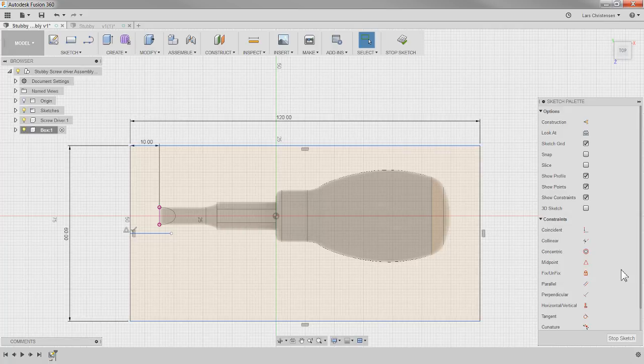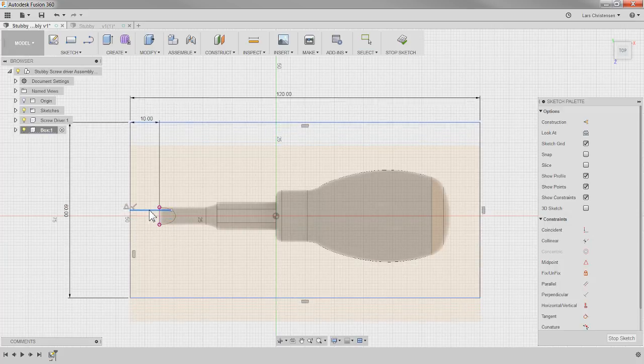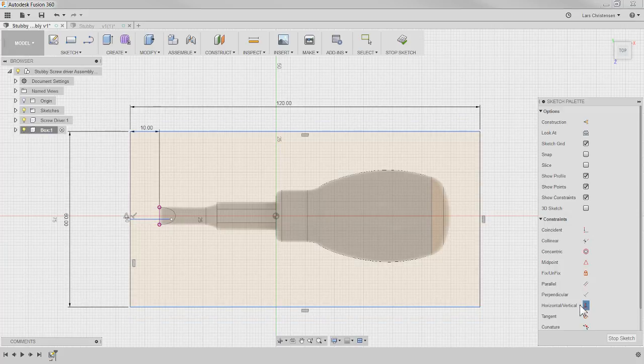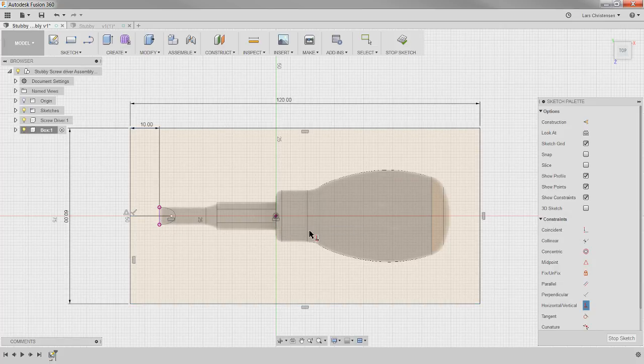And then you can do something like a horizontal constraint between this and maybe the origin, or maybe not. Horizontal from here to there. Ooh, I'm having some good issues. Horizontal from the point. All right, not the line, the point. Okay, and then I fully define that box center to that.